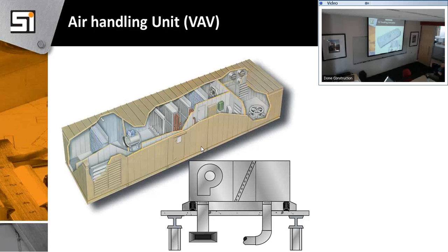So what happens now is I'm dumping all this outside air in here, and I have to get it out. Typically we have either a return fan or a power exhaust fan, and we put a static pressure controller in the building. We sense the pressure from blowing all this outside air in, and we use that pressure controller to exhaust the free air we got. Is that close enough?